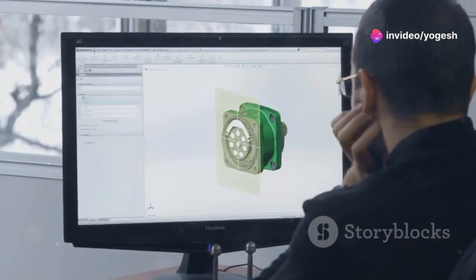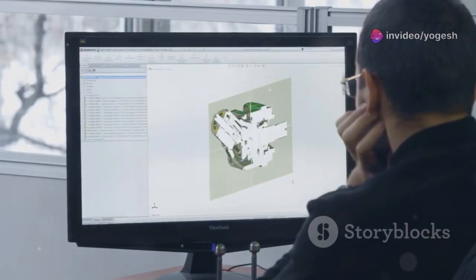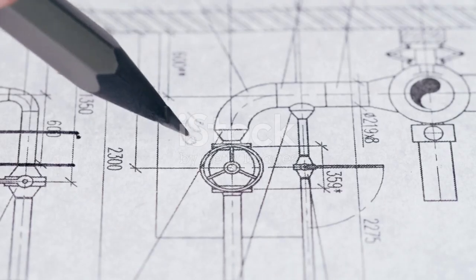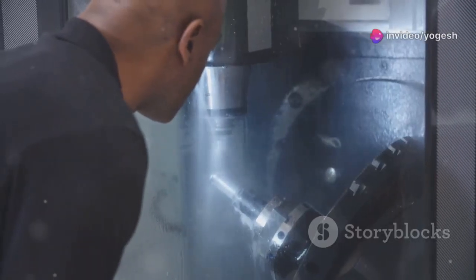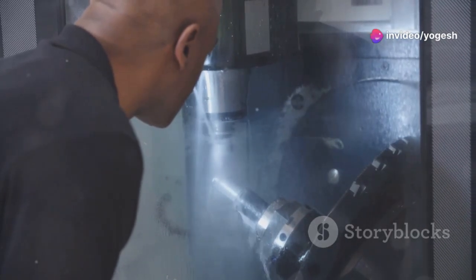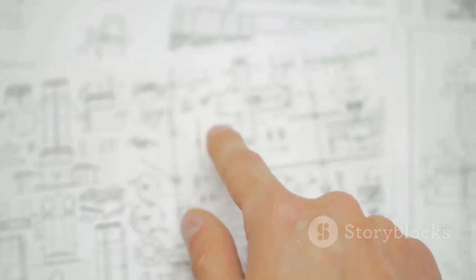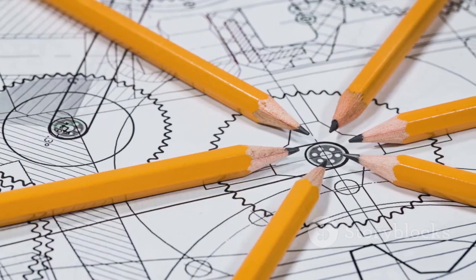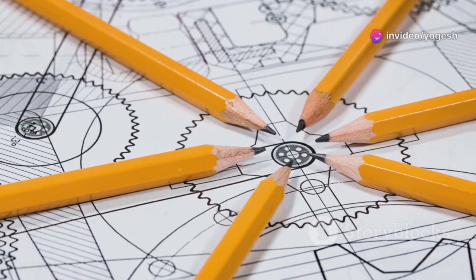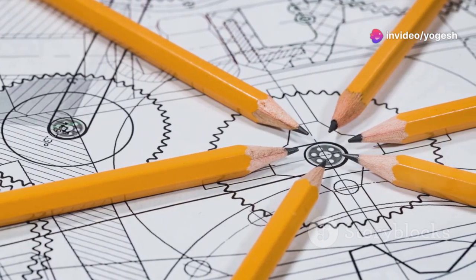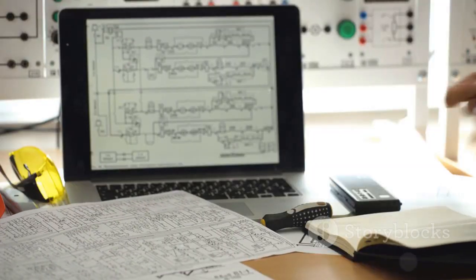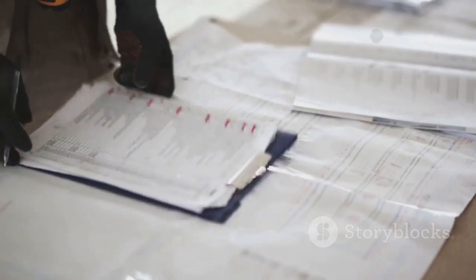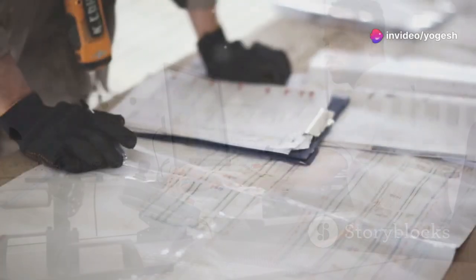Creating a spline in CAD is one thing, but how do we communicate that shape for manufacturing? Since splines don't have a simple radius, we use control points with exact X and Y coordinates on engineering drawings. Manufacturers use these coordinates to reconstruct the curve in their machines. Sometimes, drawings include notes about the curve's degree or tangency, how it starts and ends. To keep drawings clear, engineers often use a separate table listing all the points for a spline. The drawing might say, "See Table 1 for definition," and the table provides the data. This keeps the main view clean and the data organized. Reading these drawings means connecting the visual curve with the numbers in the table.